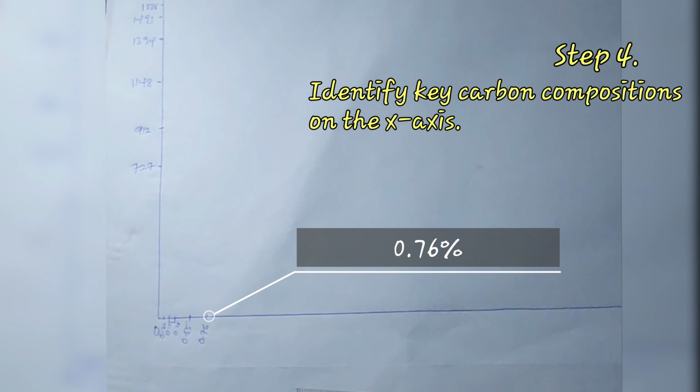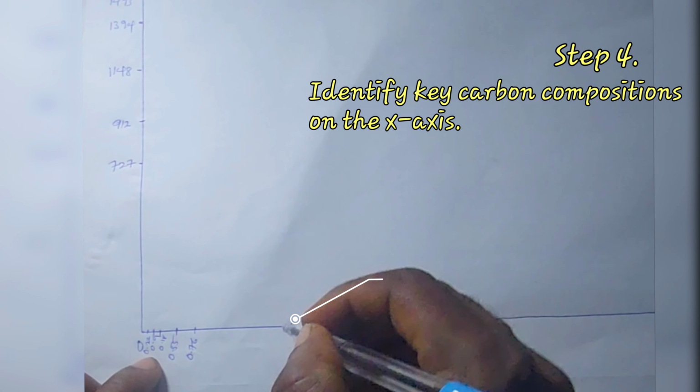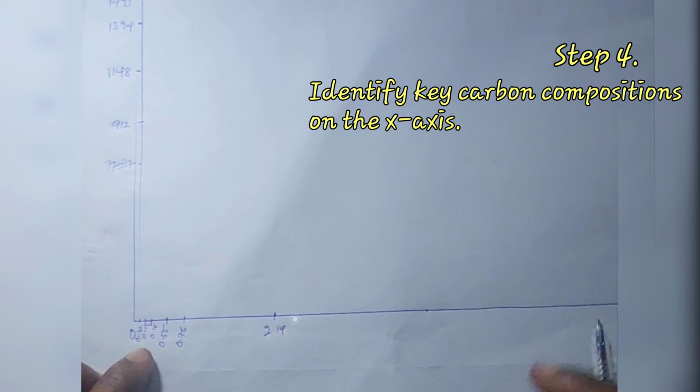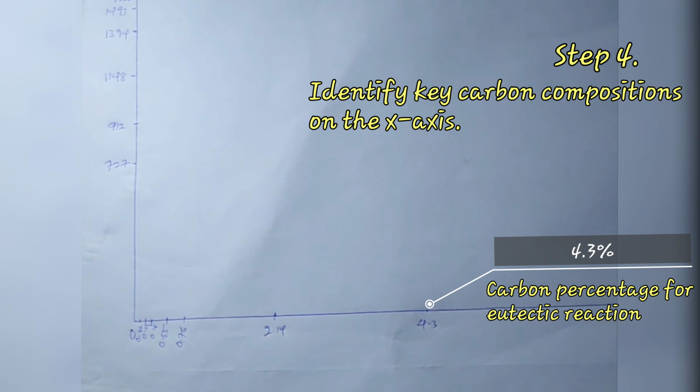0.76%. Carbon content at the eutectoid reaction. 2.14%. Maximum carbon content of steel and start of the eutectic line. 4.3%. Carbon percentage for eutectic reaction.